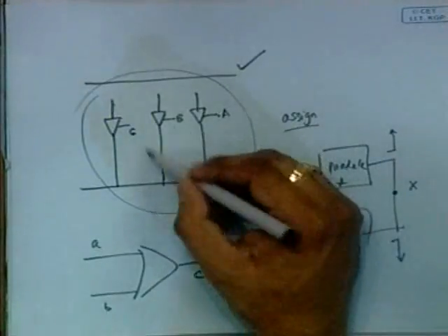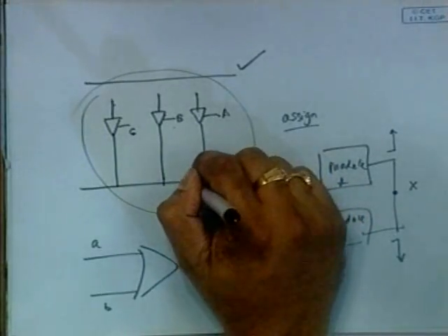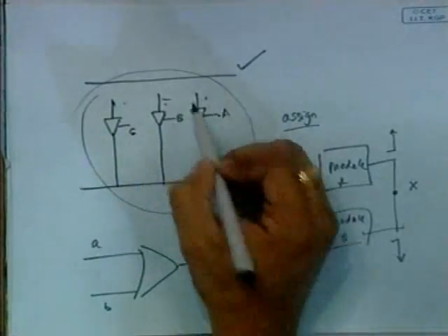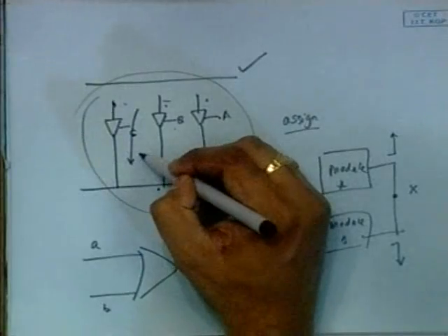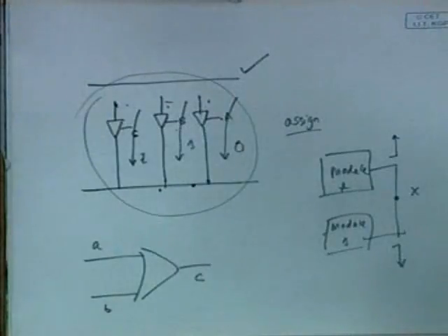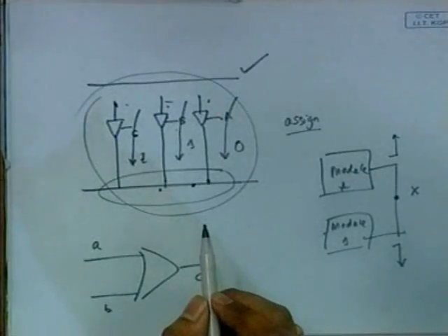As opposed to that, what we would sometimes like in our hardware would be a scenario like this. In this particular scenario I am not really trying to assign a value, but I am trying to drive a value, and there is a slight difference between driving and assigning. In a normal assignment statement, various things take place one after the other, and the last assignment stays. But in driving, all the signals which are driving, for example these three inputs, are driving a value here, right? It may happen that this is trying to drive a z, this is trying to drive a 1, and this may be trying to drive a 0. But depending upon my resolution, as I told you in the previous case, the logic of this particular bus would be determined, right?